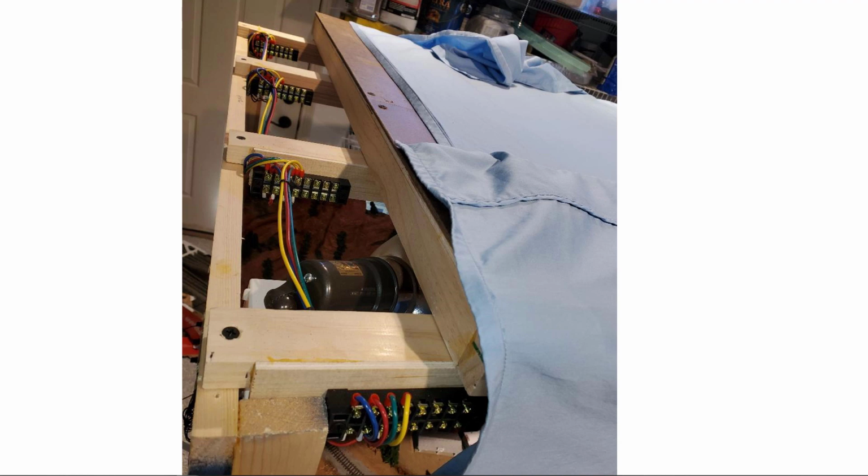Now I didn't have to use 18 gauge, but because I'm connecting all of these LED strips in parallel, that means the current flow through the wires at the far end of where you're looking, down at the other end, will be higher there because it will have all 8 LED strips drawing power through that wire. So I used 18 gauge, and I didn't have white, so I used yellow, but I used red, green, and blue for the others.